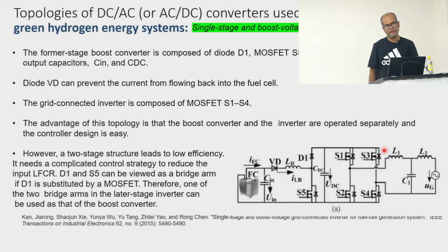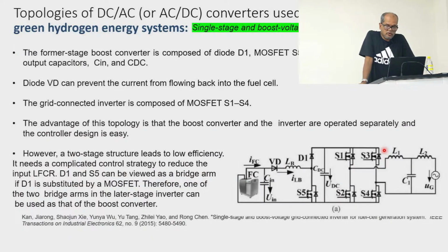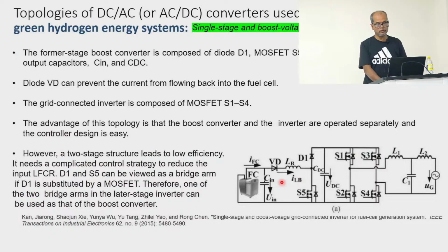So why do we need that for fuel cell application? Because as I mentioned, the fuel cell output might not be enough, just after the inverter, to match the required voltage on the AC side. So that's why we always use a boost with the inverter.